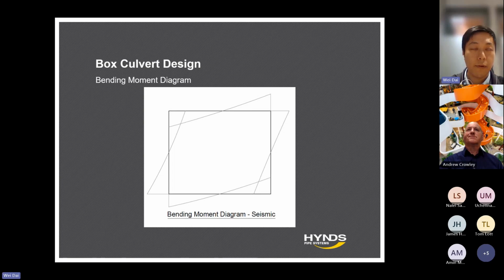So eventually, after the racking analysis, we'll get a bending moment diagram as shown on the screen. You might notice that the bending moment will appear at the internal face, internal corner, and external corner of the box culvert. So we will need to detail the reinforcing to cater for those bending moments at these locations of the box culvert.